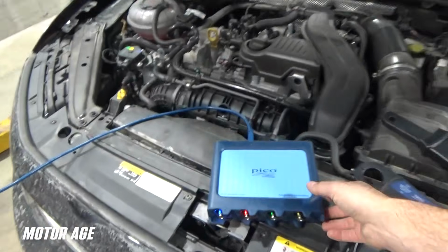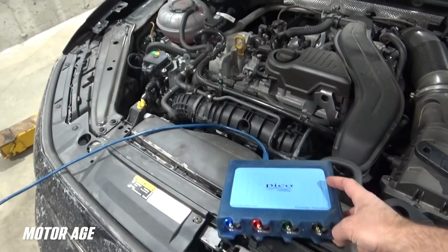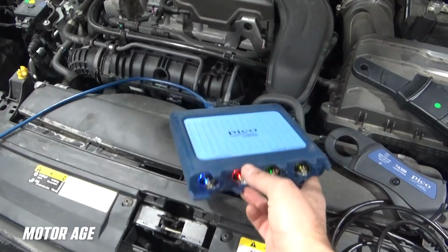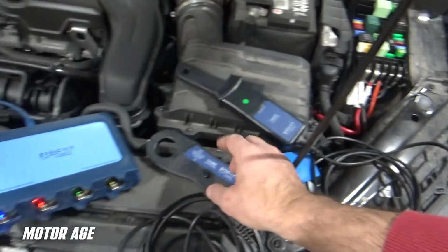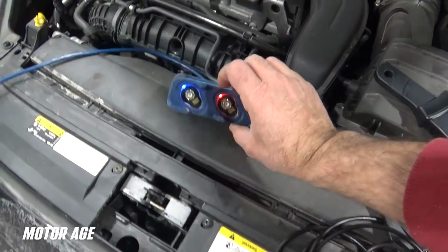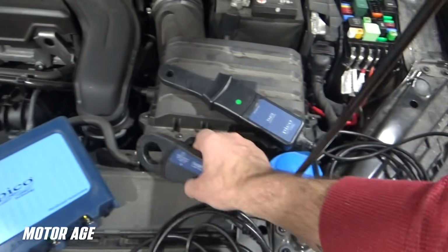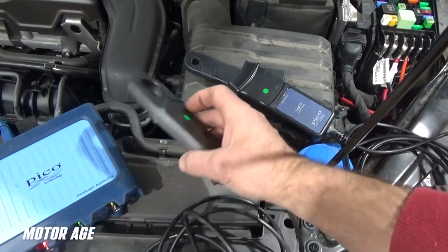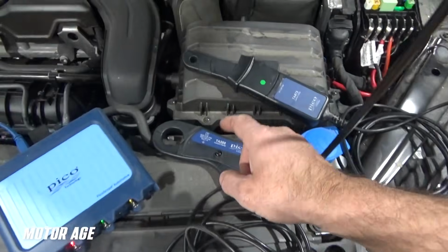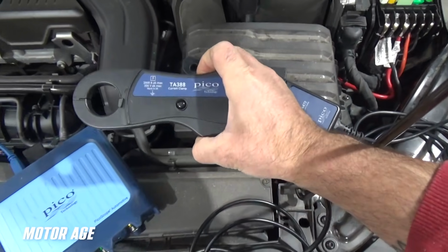So this is the PicoScope 4425A multi-trace lab scope. And among other capabilities this scope boasts, what I want to show you here is that this allows us to carry information from the device we're using, in this case some amp clamps, to the scope just as any other scope operates. But what's unique about this is it not only powers up these devices, so we're no longer changing 9-volt batteries in these things every time we forget to turn the switch off, but it also allows this tool to communicate with these, and they self-identify.